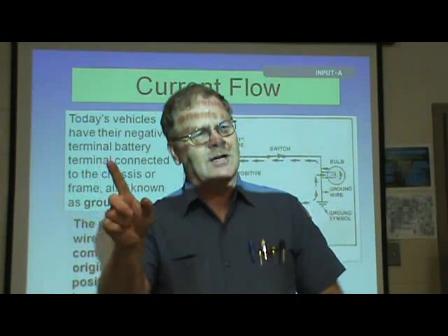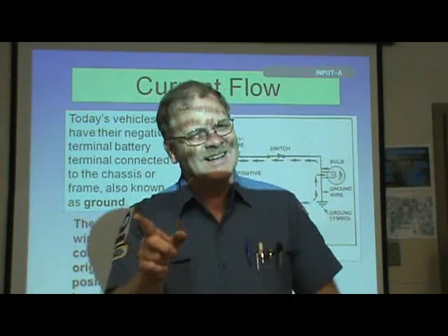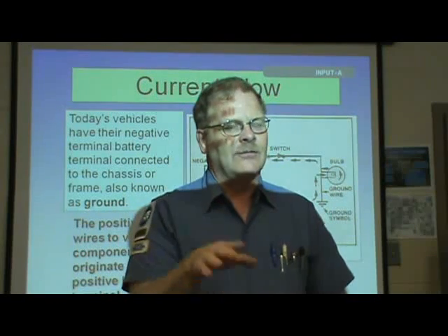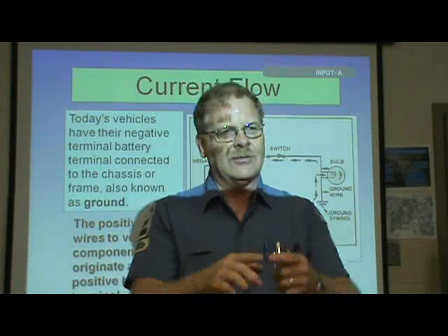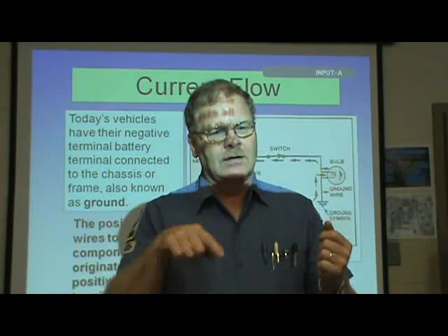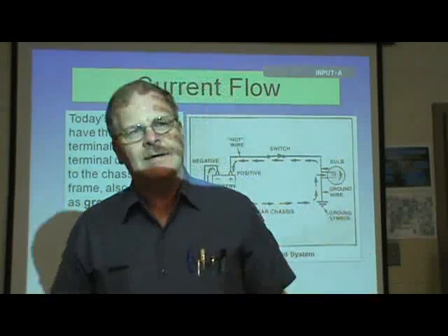And then as you stopped, it would come back. It would act almost like a speedometer. It was crazy. And so whenever I saw them doing that, I'd always look at that ground by the right front wheel, and you'd see that it was broke. And so I'd have to take a skinnier, more pliable wire and make a ground, because it didn't have to be that big.